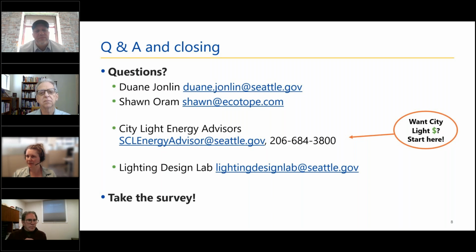Okay. And Duane, Alex has a question for you too. You briefly mentioned on heat pump water heaters the utility data connection. I have a few projects that use the C406.3.6 hot water energy storage and understand the energy storage. Was curious if there's a way to know when the utility will provide the peak input and how long it will last. So this is not a data connection that will be connected up right now. There's nobody asking for it.